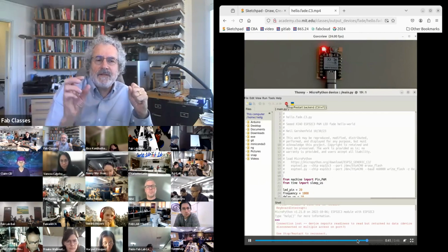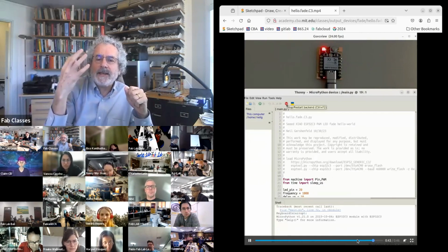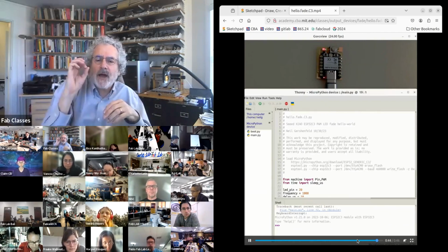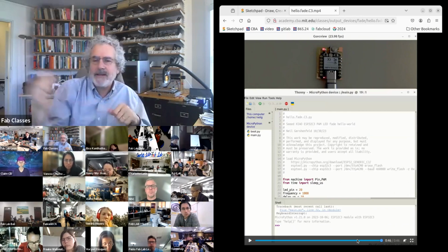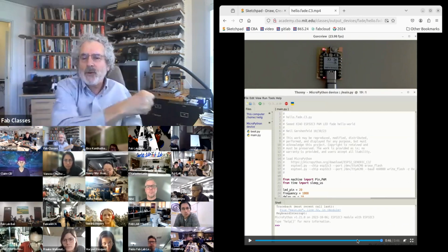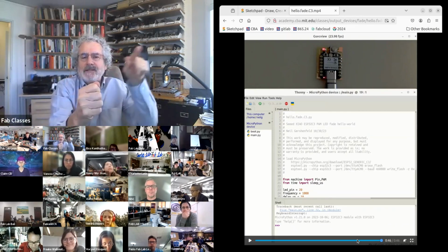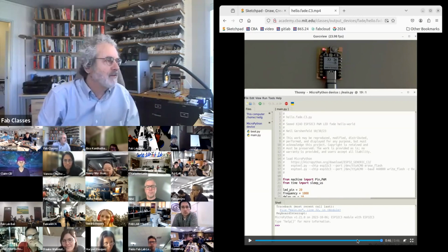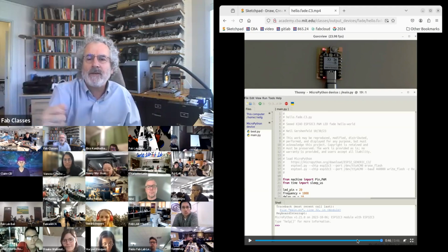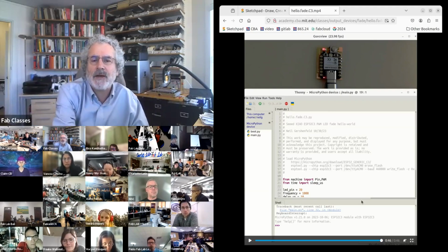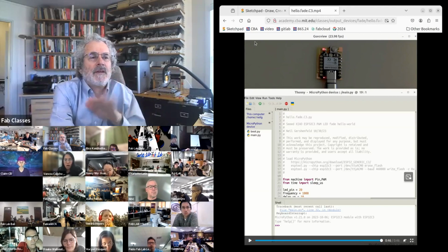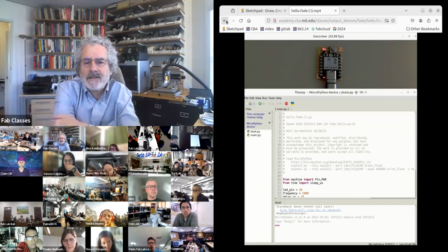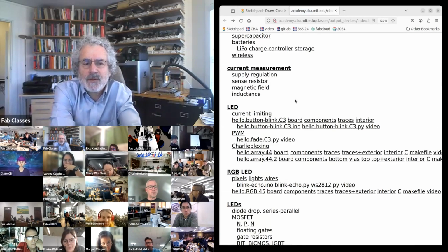And then your eye can't respond this fast, so your eye just sees the average brightness. Now, if you take a PWM LED and you wave it really quickly, you'll actually see the separate pulses because they're occurring at different spaces. So if you move your head quickly or you wave it, you can tell if it's being pulse width modulated. But if it's not moving, your eye just sees the average intensity. So that's PWM.